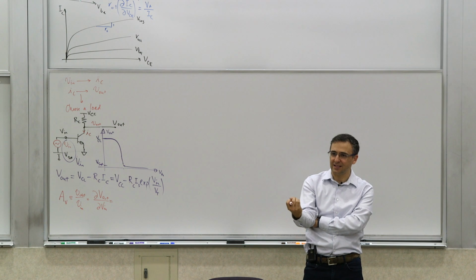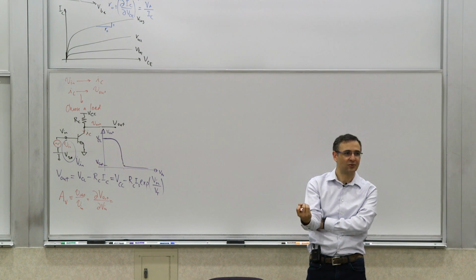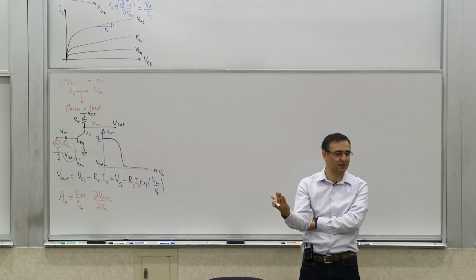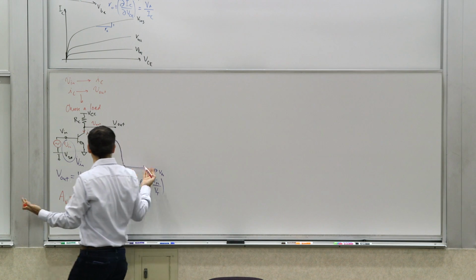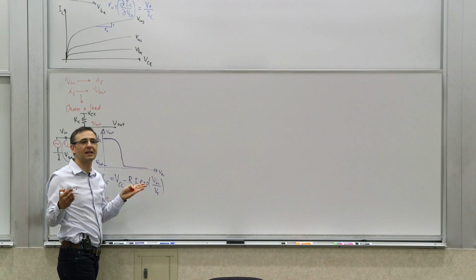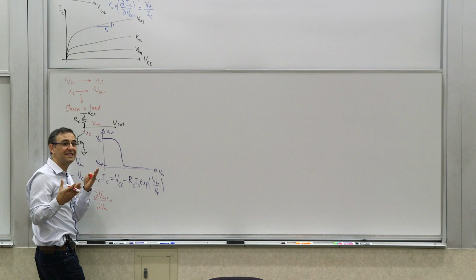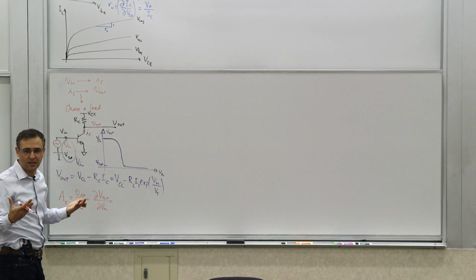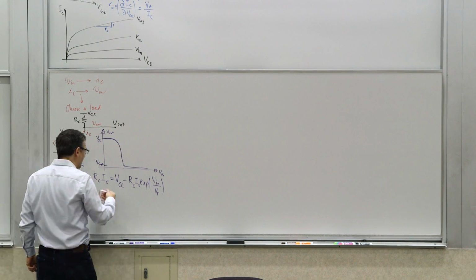So now, depending on what kind of source you have, that 0 may mean a different thing. If you have a voltage source, that 0 means a short circuit, short circuit to wherever it's connected. If the other terminal is connected to ground, it becomes ground. If it's a current source, it is an open circuit, right? So this derivative being 0 means that those independent sources in AC, if there's a DC independent source like a battery or current source and things of that sort, they become 0. And whatever that 0 means depends on the nature of the source. But anyway, let's do the derivative.